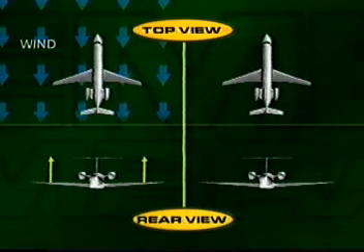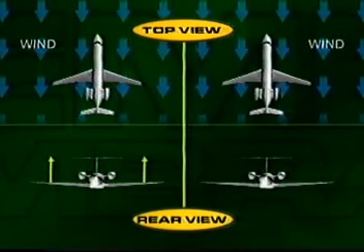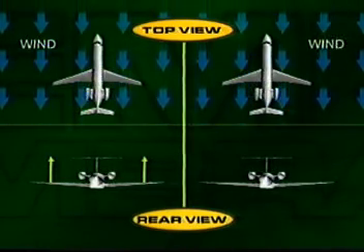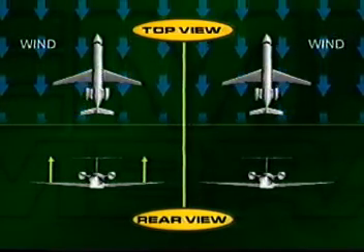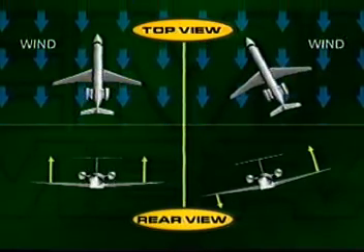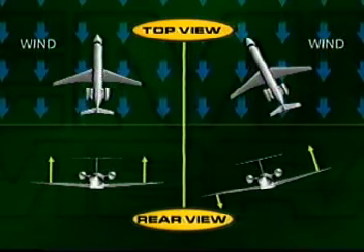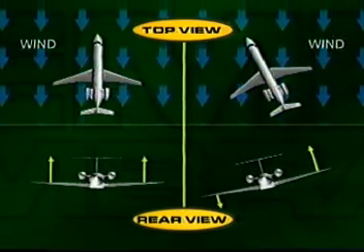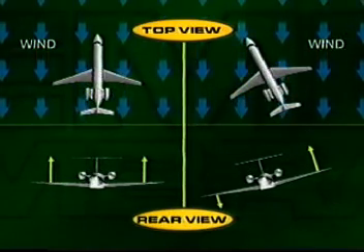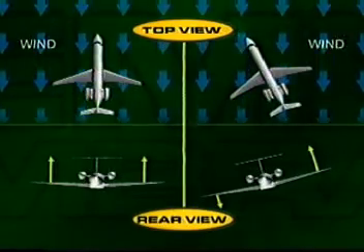When the aircraft is yawed, the inside wing is slowed down and the outside wing is speeded up, therefore unbalancing lift in each wing separately, resulting in aircraft roll. The outside wing produces more lift because it is effectively less swept, while the inside wing loses lift because it is more swept. This contributes to further unbalanced lift, and rolling is exacerbated markedly, adding to the actual geometric dihedral.